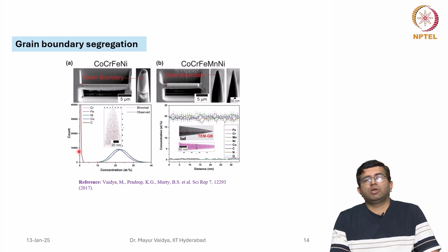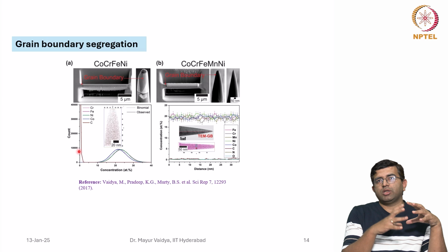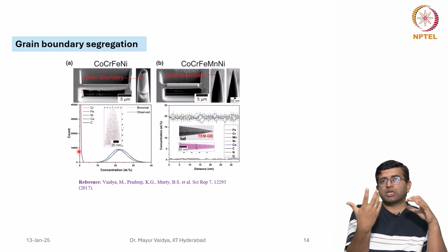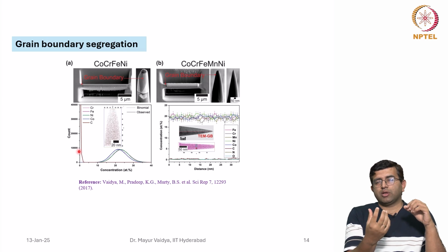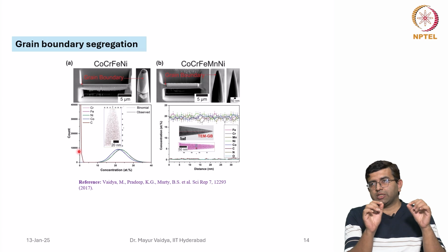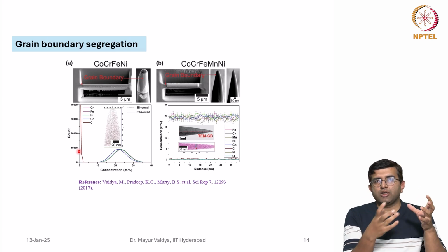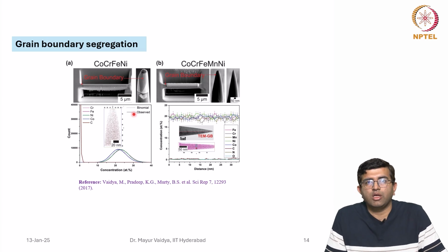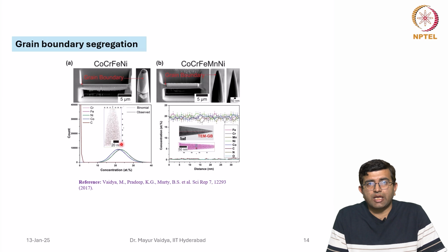Then for measuring the grain boundary diffusion, it is also important that the segregation is absent. So, such alloys have also been studied before the diffusion to ensure that the segregation is absent. This has been done in combination with transmission electron microscopy and atom probe tomography, where you can see here, for example, in this boundary that there is no segregation of atoms present. Similarly, here as well.